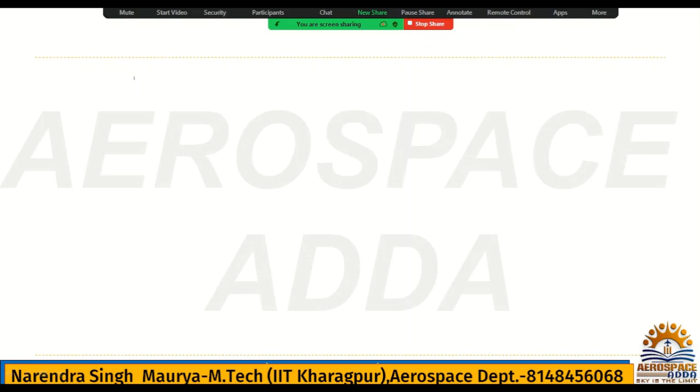So I can write that in space Pa will be 0. Alright, so now what is the thrust? This thrust is nothing but m dot p into Ve plus Pe into Ae.